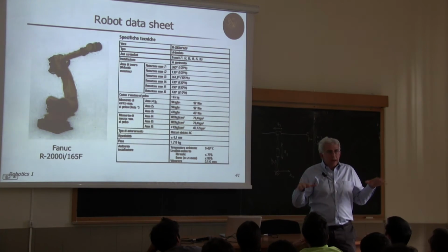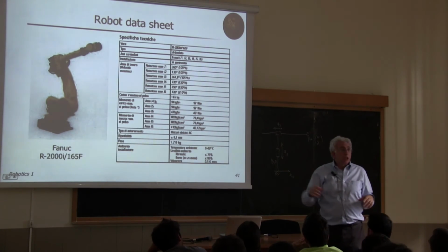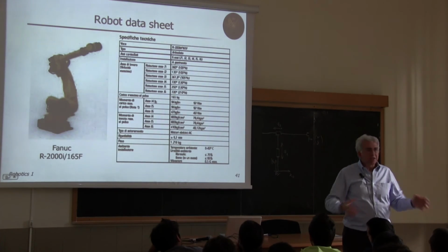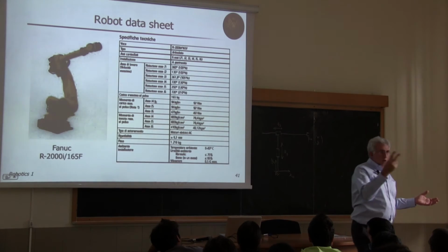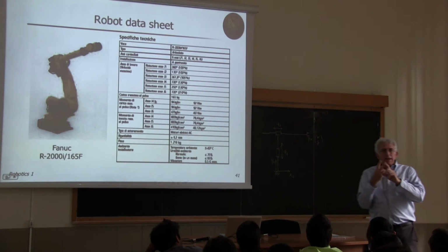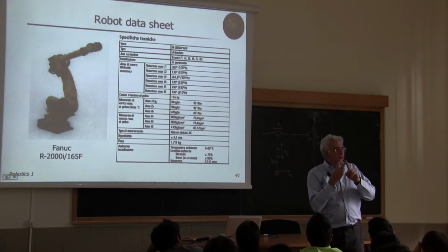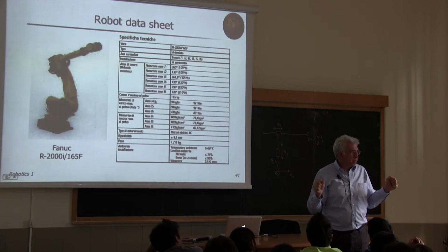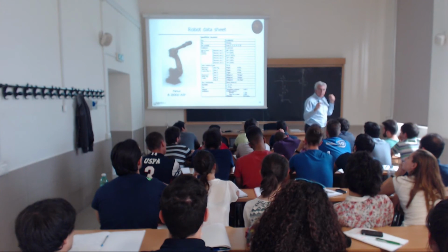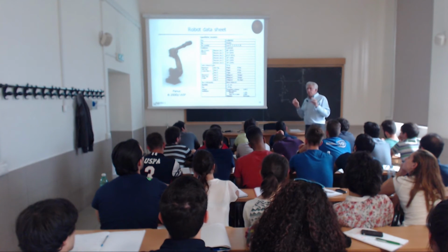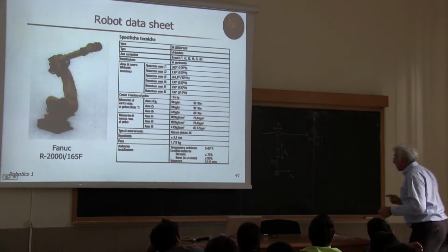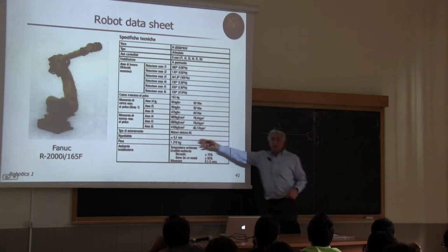Now, if you take with this robot a payload which is not 160 kilograms, but 250, what happens? Does it crash? Well, there are two things that happen. First, if you don't exceed the limit currents in the motor so that protection starts and everything breaks down, the robot will continue to operate, but there is no guarantee of obtaining this accuracy and repeatability.